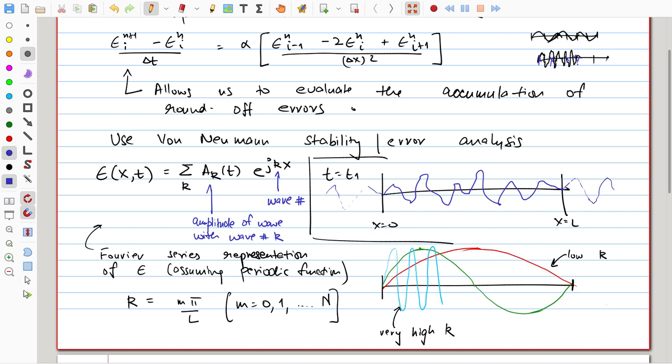And this is the idea of sampling. Have we learned about sampling? People in this class? Sampling frequency and so on, yes, right? The best frequency you can capture is dependent on the number of sampling points you have. You cannot have more information than that, even though the actual signal could be fluctuating at a higher frequency than what you can capture, but that is lost. Similar is the idea here. So m can max be N here, nothing beyond that. You can have a larger m, but those contributions would be 0 because you cannot capture that in this situation.